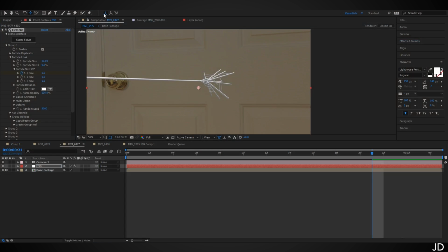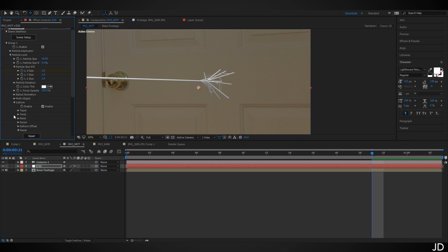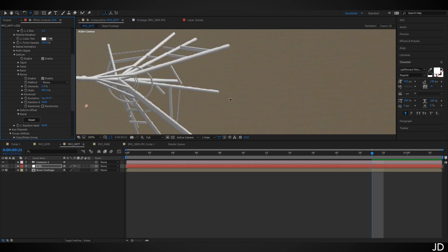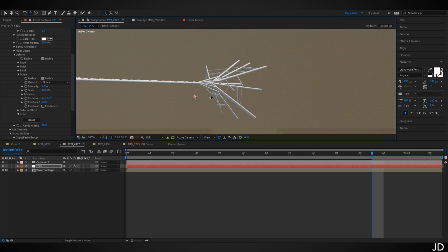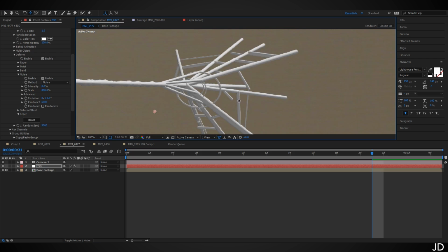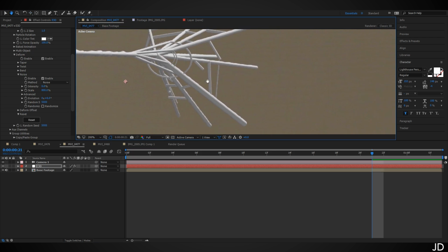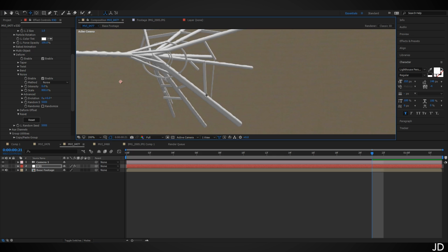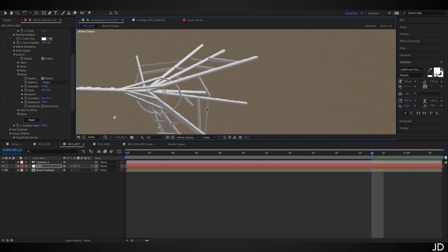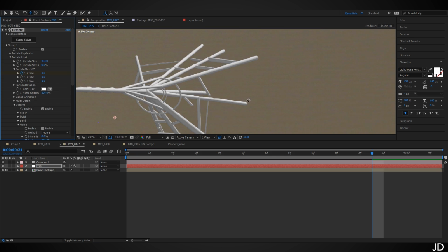The next thing that we need to do is in the particle look rollout, go down to Deform, enable that if it's not already, find Noise, enable that as well. And then we're going to turn the intensity up to maybe about 0.8, and then the scale up to about maybe 800. That looks pretty good. And just like in part 1, I'm kind of pushing through this quickly for the sake of the tutorial. Some of this needs to be refined a little bit further, such as I don't like that we can see this ring perfectly. This strand's a little bit thick, as well as this one below it. Little things like that I'm going to leave alone for now. However, it's up to you guys for whatever you think looks good for your project.